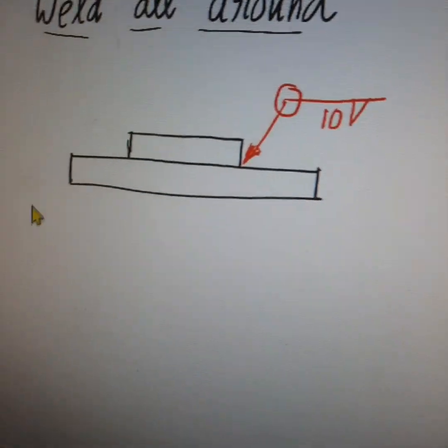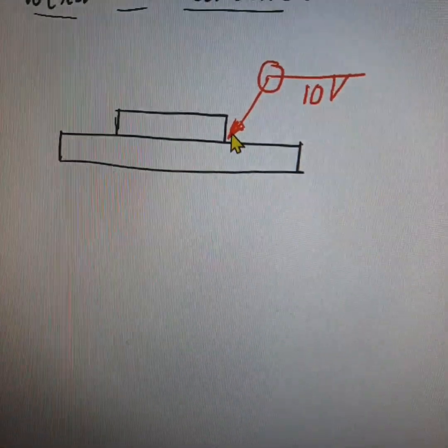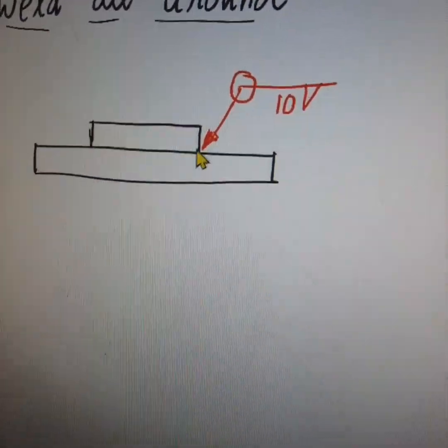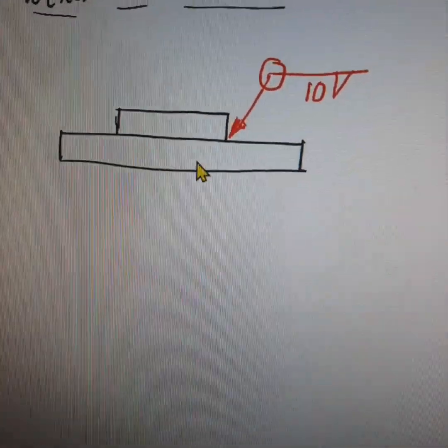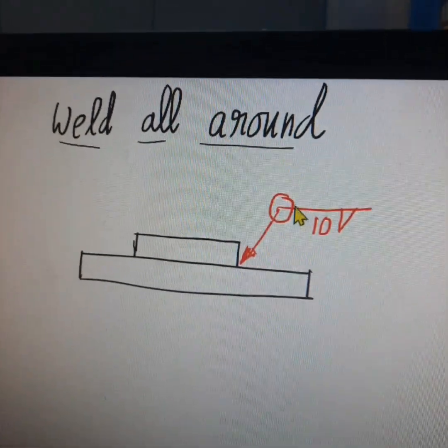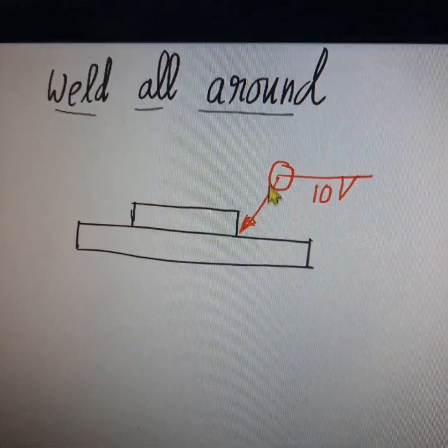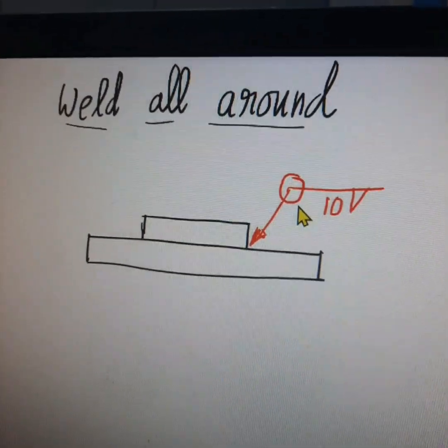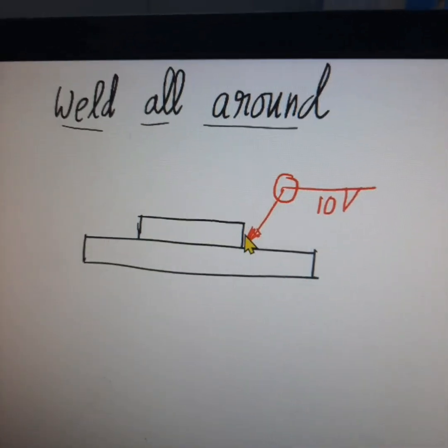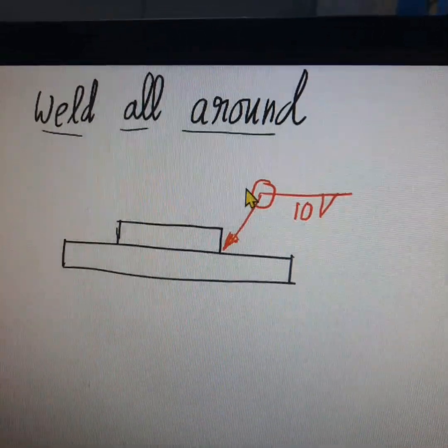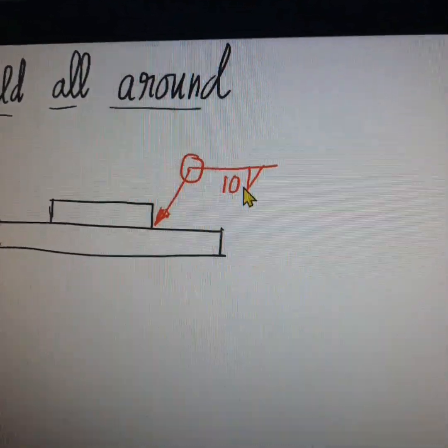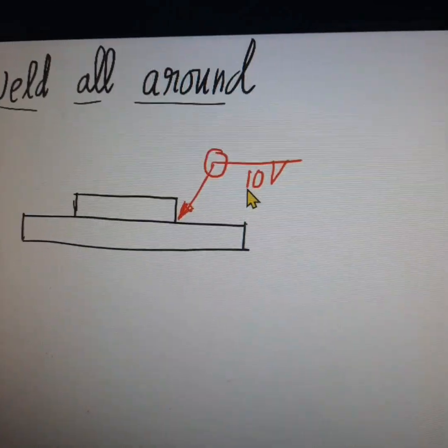Draw the orthographic view of the two circular plates, and you want to perform a fillet weld of size 10 mm. Since the welding is to be done all around the perimeter of the smaller circular plate, you use a weld all around symbol. This is the symbol, a circle drawn at the corner of the two lines. This shows welding is to be performed all around the circular plate. The type of weld is fillet weld, and for this example, the size of the weld is 10 mm.